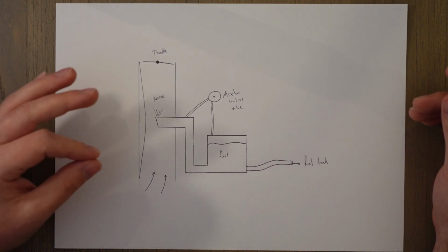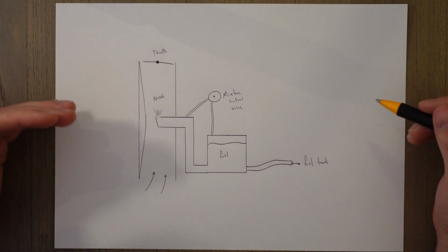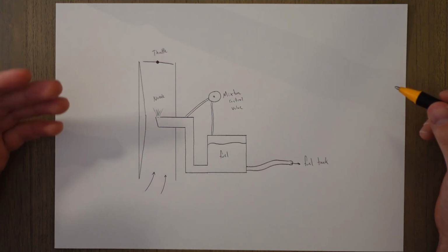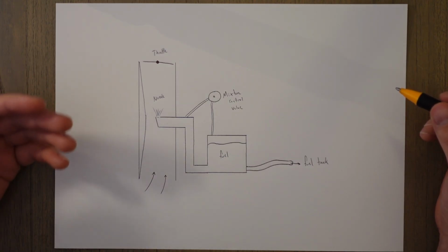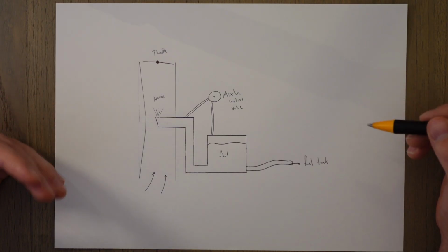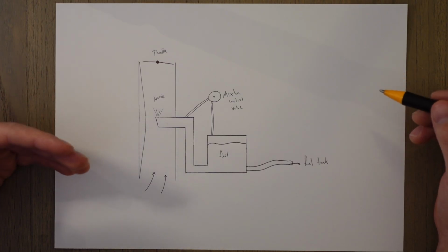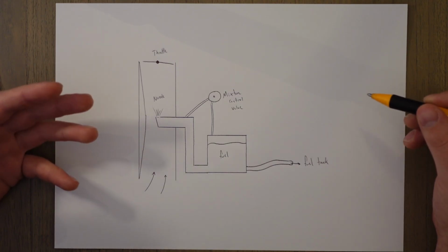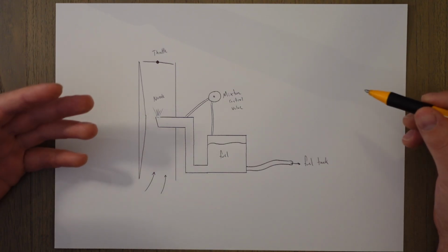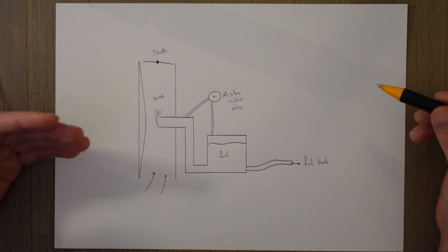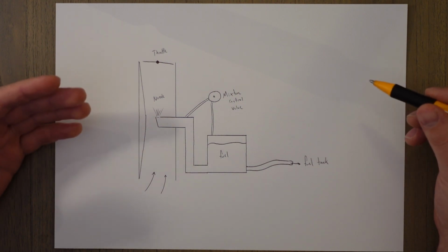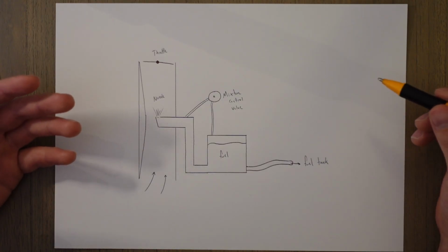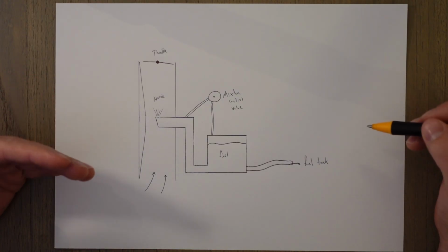The chemically correct mixture for fuel to air is about 15 parts air and 1 part fuel, but this comes with the risk of detonation. So what we can do is add or reduce the amount of fuel in the mixture. When we add fuel and make the mixture richer, then the excess fuel that isn't used for that chemically correct combustion is used to cool the cylinder instead. The excess fuel absorbs the latent heat and brings the risk of detonation down.